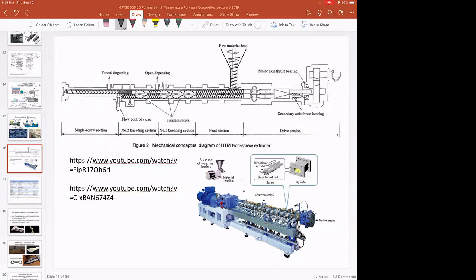So you can buy composite filaments, you can buy composite feedstocks, but if anyone has done a lot of material extrusion AM of composites, in this class, they'll know it's not easy. And because most polymer products that you buy out there are some kind of composite, really thinking about how you might want to AM composites and what it's going to take to AM composite materials is really important. So you can check out these diagrams if you want, but there's a lot known about composites generally in the polymer industry. Now we need to translate that knowledge to AM, and that's what people are working on.